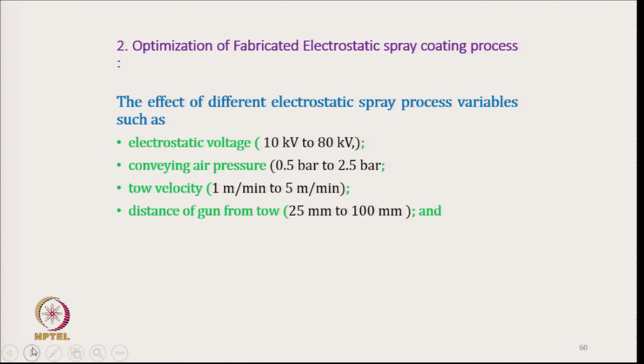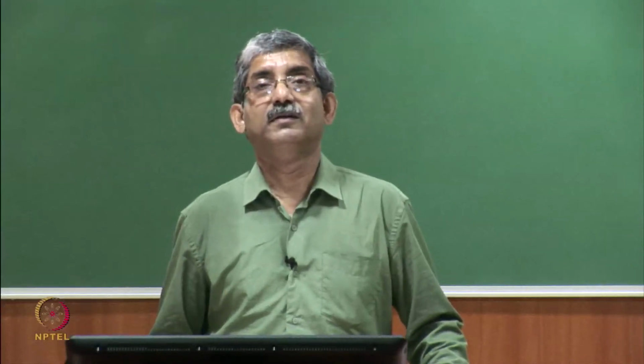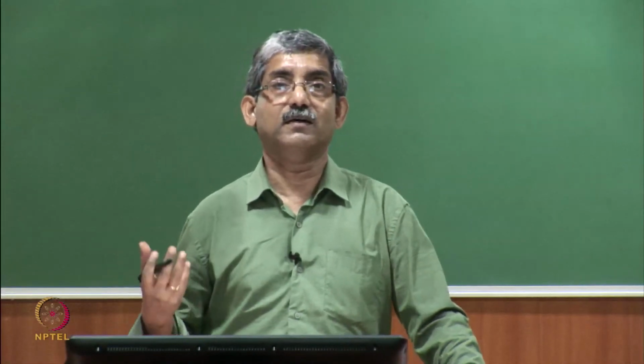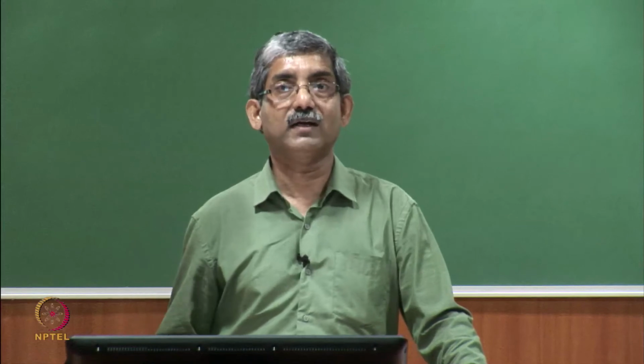Distance of the gun from the toe is very important. That again affects the volume fraction of the carbon fiber, that is the matrix content we can vary.